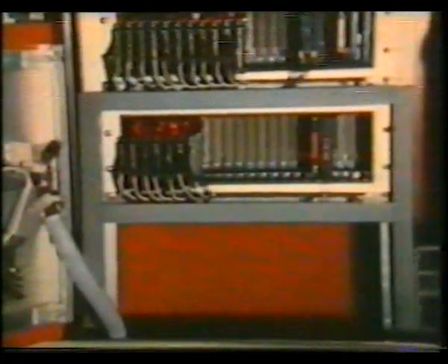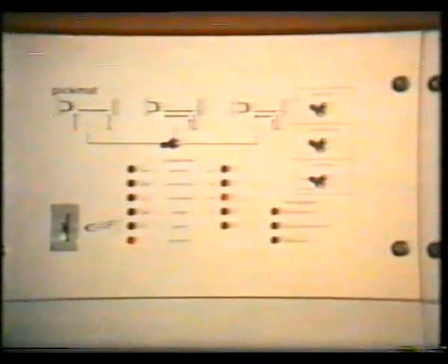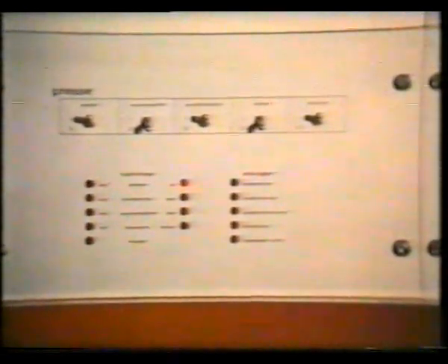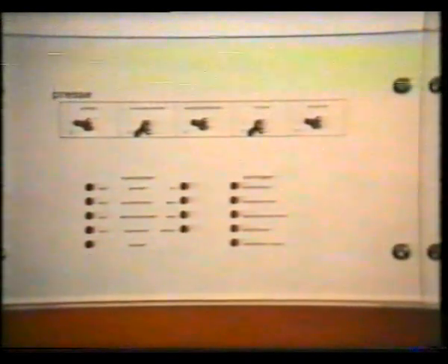The control system of the module mat production unit, which is independent of the die casting machine, is freely programmable and offers maximum flexibility and operating convenience. It ensures central control and monitoring of the extraction unit and the trimming press. Signal lights allow the automatic production process to be supervised at any time.